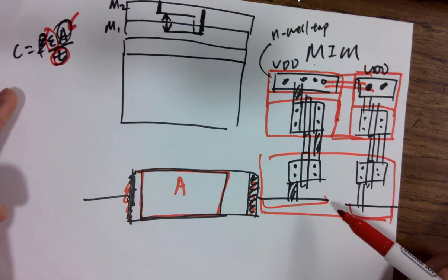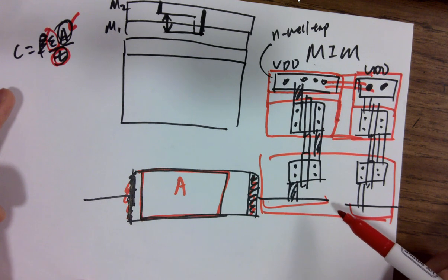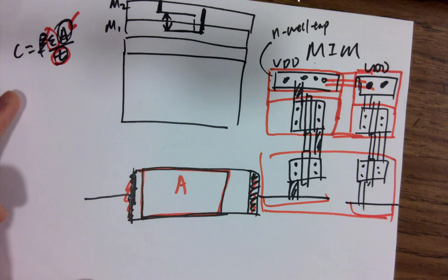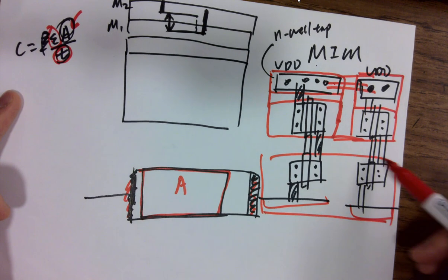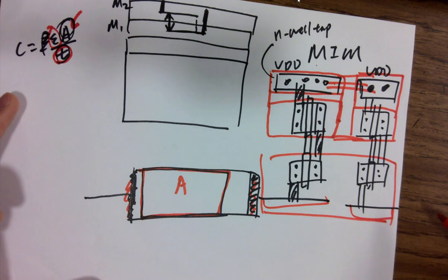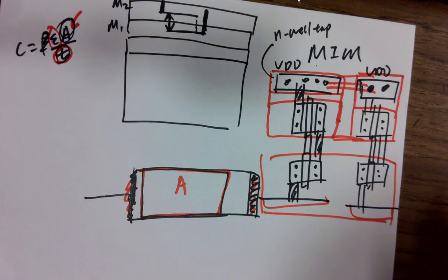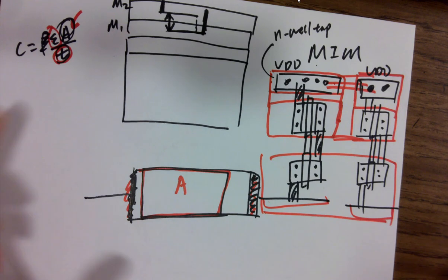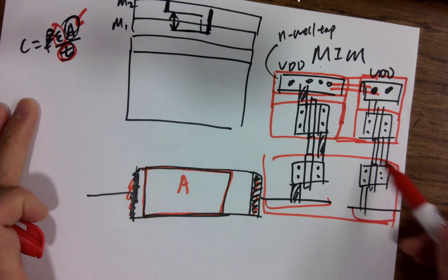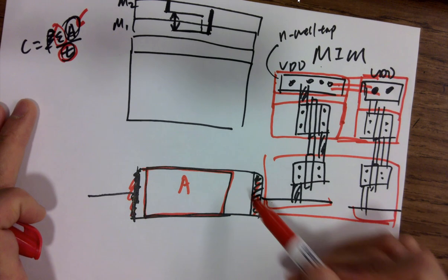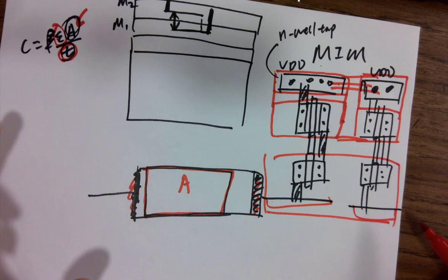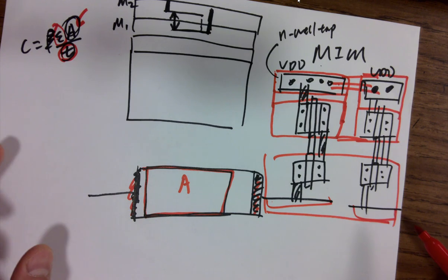No, it's just the P substrate, it's just the wafer itself. But for the foundry, we still want to draw it. That will be a lot better, or required sometimes. It's not reporting well errors. So the foundry knows that all these devices and taps are being placed in the P substrate without any other things to cover it.